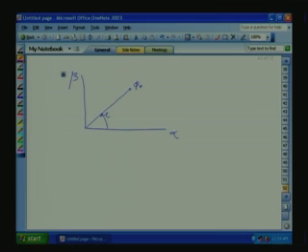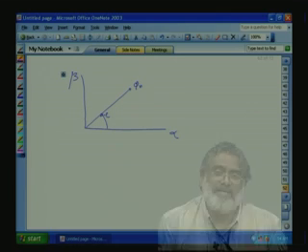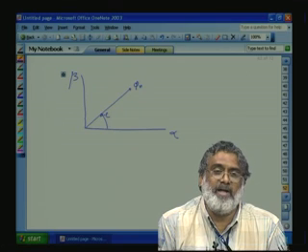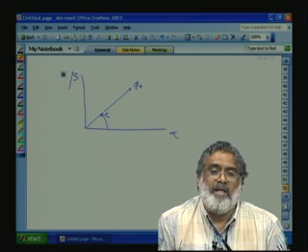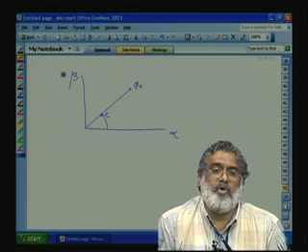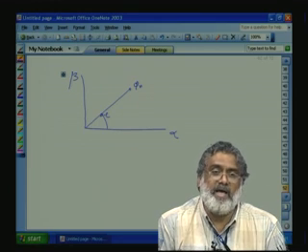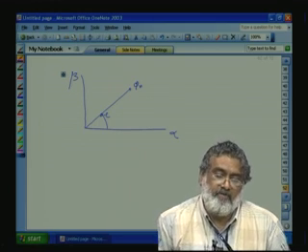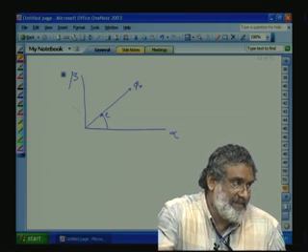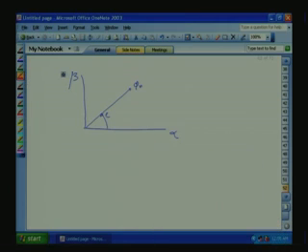Now, for vector control applications, as I told, IS we have to define with respect to psi r, that means the component along psi r and perpendicular to psi r we have to find out. So, we define another axis, a dq axis. This is d, this is q. This d is along the psi r axis.